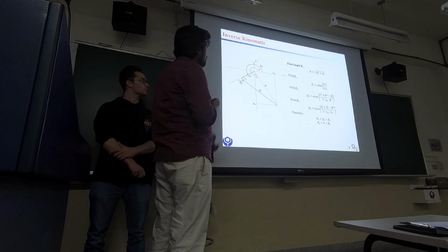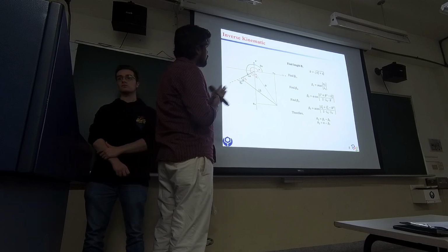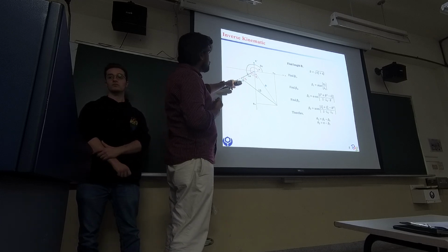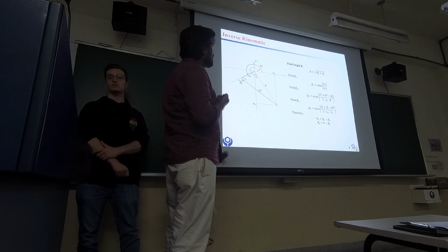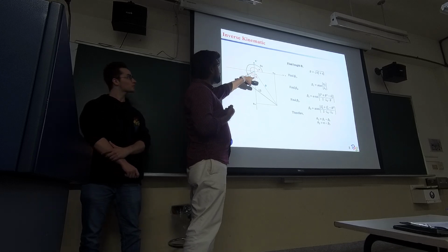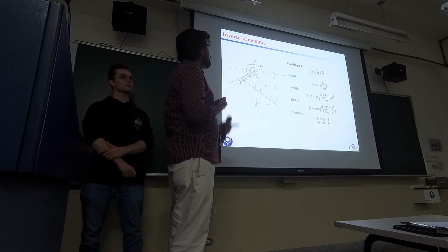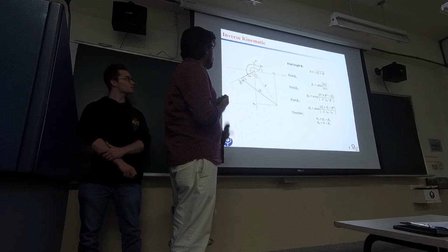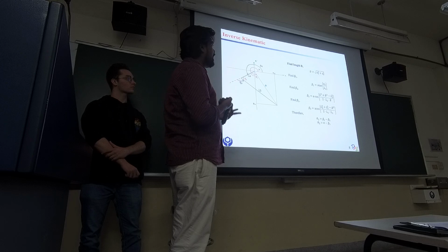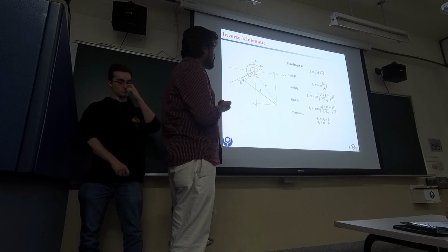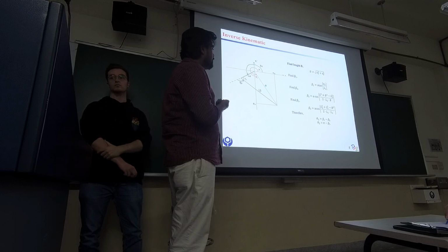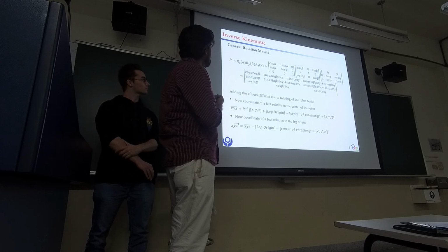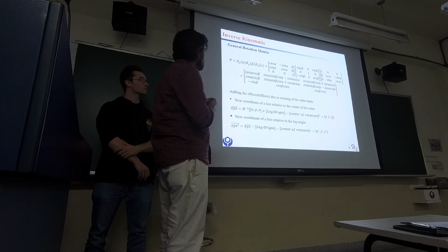And now we are seeing our robot leg from the side view. Then how will it look? Now we will find theta 2 and theta 3. From what I mentioned previously, as we found A, we also find the value of B, which is the square root of x squared plus z squared, and we also find beta 1 equal to arctan of z2 over z1, like beta 3. Theta 2 will be beta 1 minus beta 2, and theta 3 is equal to pi minus beta 3. And this is the general rotation matrix I mentioned that we use for the calculation.